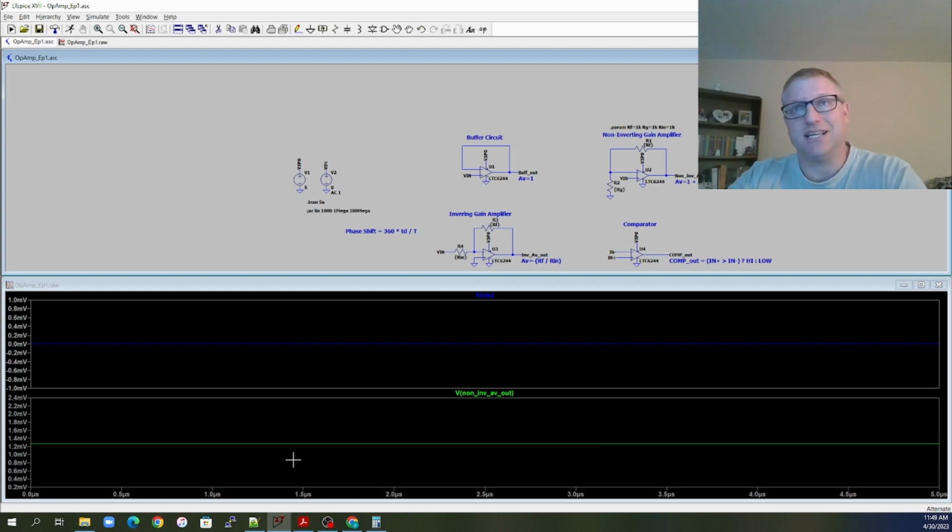So the spec sheet said that it was about 100 microvolts, depending on what the thing is. They may have done the specs on the DD package, because if you recall, the DD package was a little bit closer to the 1 millivolt. And they may be doing it at ambient temperatures or elevated temperatures, something like that. But you can see it here. And so if you try to do simulations with that, where you're trying to do too much of a high gain, that offset will mess you up.